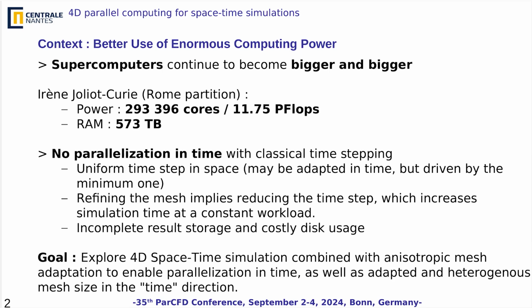Another observation: in classical time stepping, there is no time parallelization. We do that step by step, and we can adapt the time step, but it's driven by the minimum one in space. So it's a uniform time step in space. When we refine the mesh, you also most of the time have to reduce the time step. And if you want to keep the same workload on each core, the simulation time will double